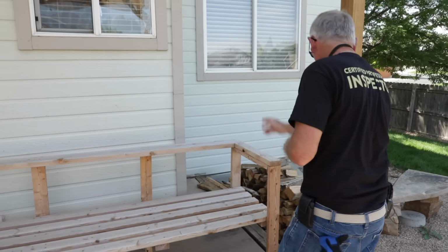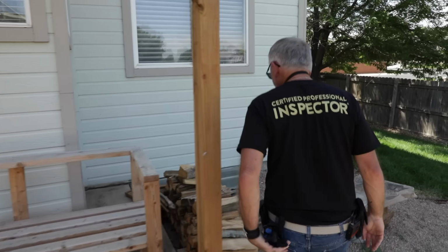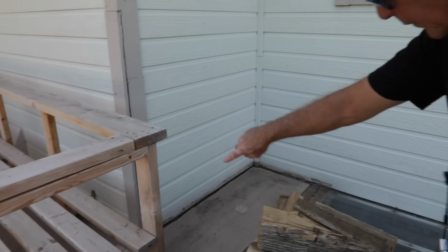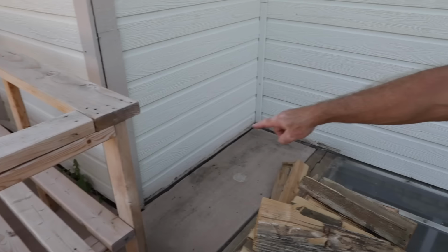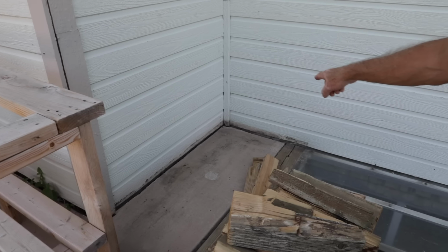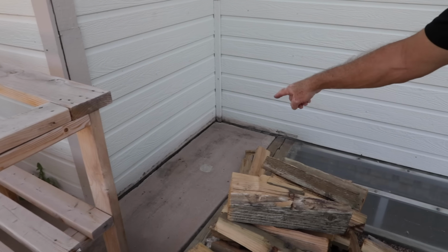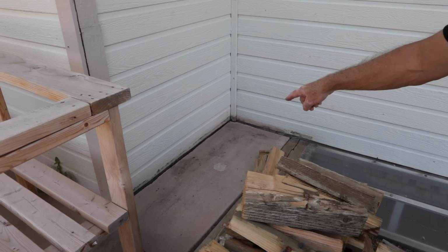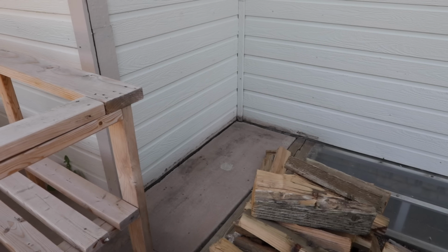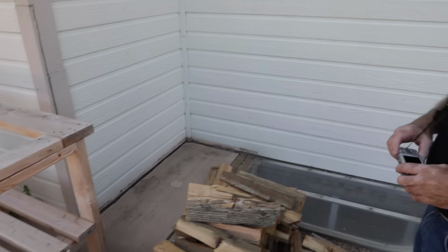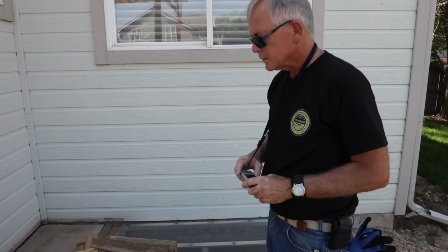And if I look around the corner, we got a crack here on the corner, some substantial settling next to the house, anywhere from 2 or more inches. Again, I see an attempt at a mud jacking repair here, but they just didn't get it done. So I'm going to recommend further review by a concrete contractor.